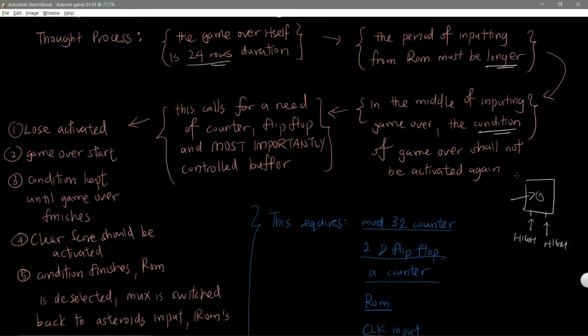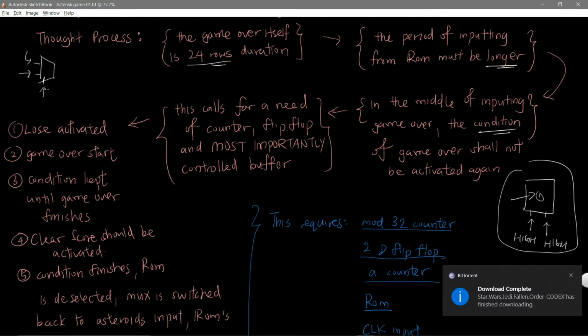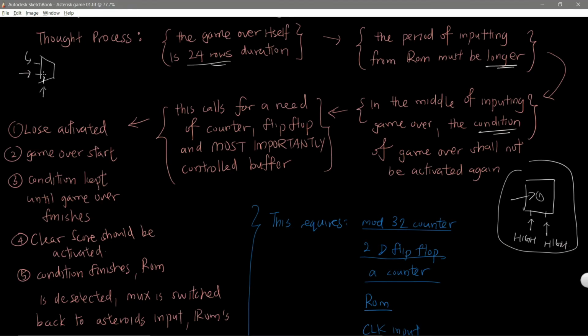So you want to use this small component here to lock your mux controller. This is going to control the bit select of your multiplexer. The bit select decides whether to take from this input or this input. And yes, that's all. It's either 0 or 1 because we only have 2 inputs to choose from.